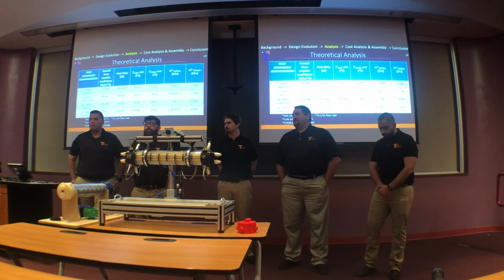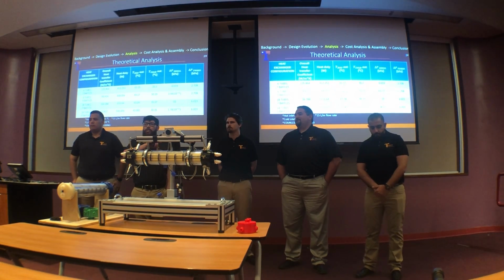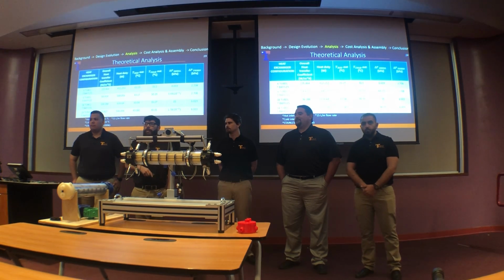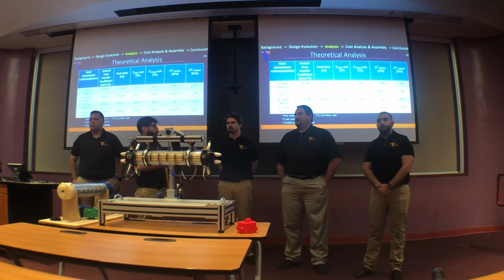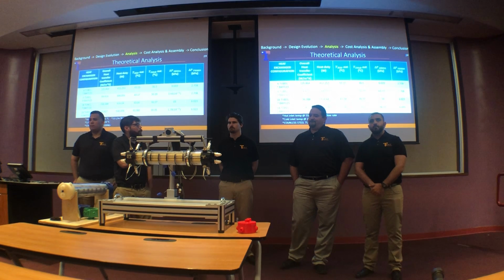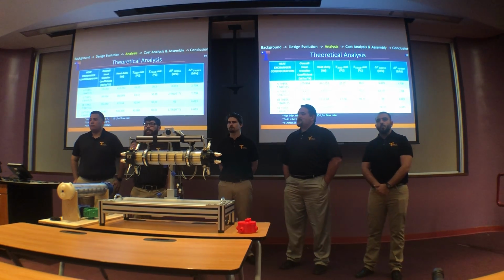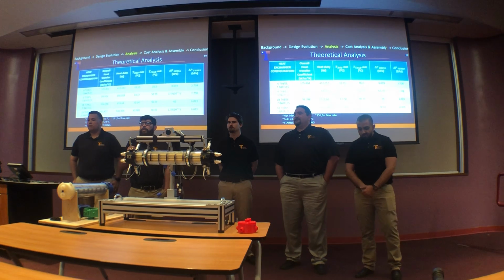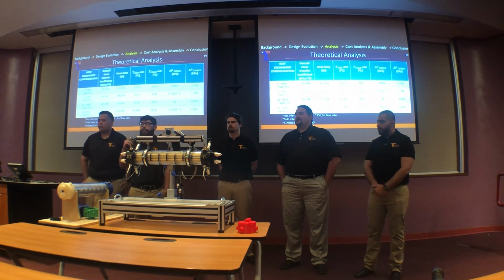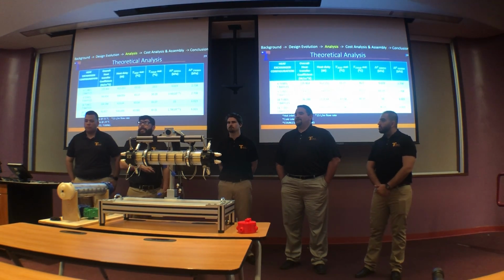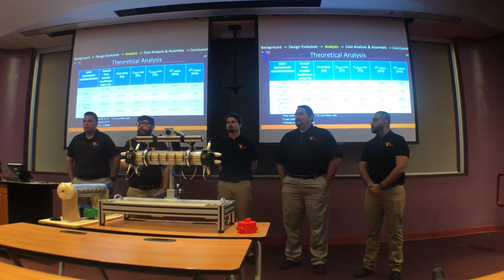And then as a more realistic configuration, we did each tube set with 7 baffles. And so you can see from our output values, there's a nice predictable gradient, with the 18 tube 7 baffle configuration having the highest heat transfer, and then the 6 tube no baffle configuration has the lowest heat transfer.